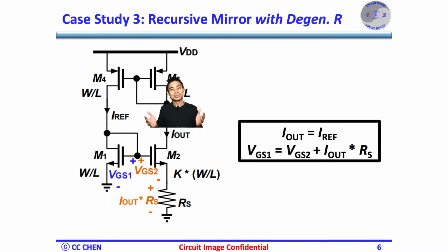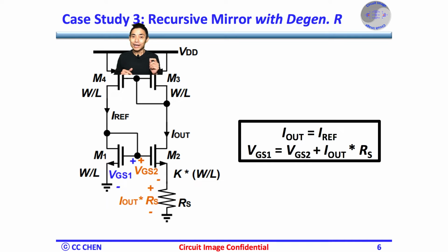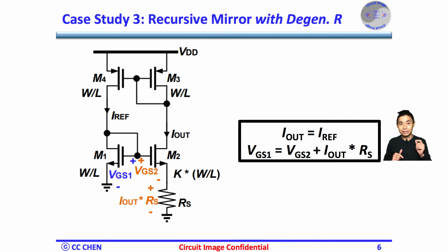In addition, the device sizes of M3 and M4 must be the same, since the current IR of the diode-connected M3 should mirror the current IR back to the M4 without any source degeneration resistor. The operation image will not only show the size of the 4 devices, but also identify the 2 defined equations. IR equals IREF.